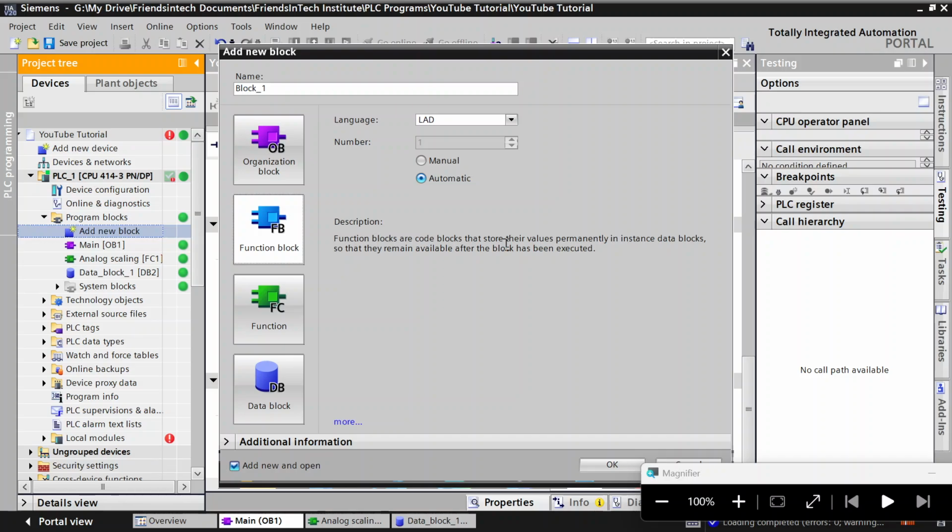Instead of developing 5 latching circuits or latching diagrams, one for each motor, the only thing you need to do here is develop one, then call it 5 times. If you have 5 fans. If you have 20, call it 20 times. That is what is called a subroutine. A subroutine is used to implement repetitive tasks.